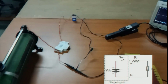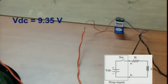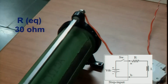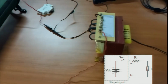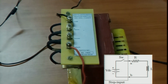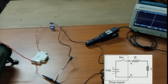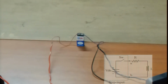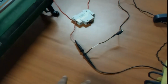So this is essentially what we are going to do. The voltage is a battery of 9.35 volts, that explains why I chose the value of 9.35 in my simulation as well. The R of the rheostat is 30 ohm, whereas the inductor is 60 millihenry. These are the kinds of values we used in our simulation as well. The inductor also has some resistance, so we can expect that there will be some difference between what we see here and what we got in the simulation.